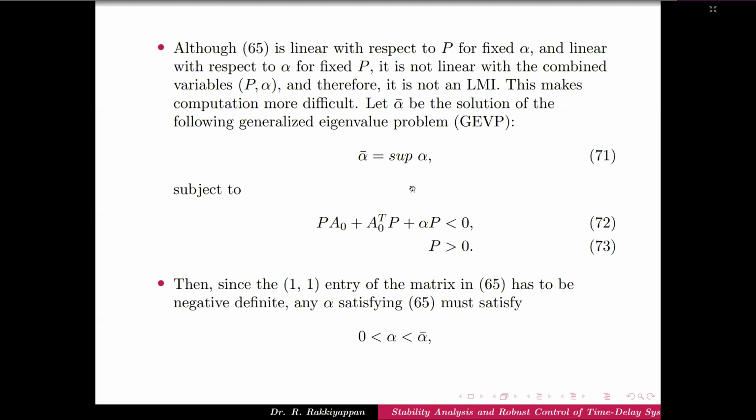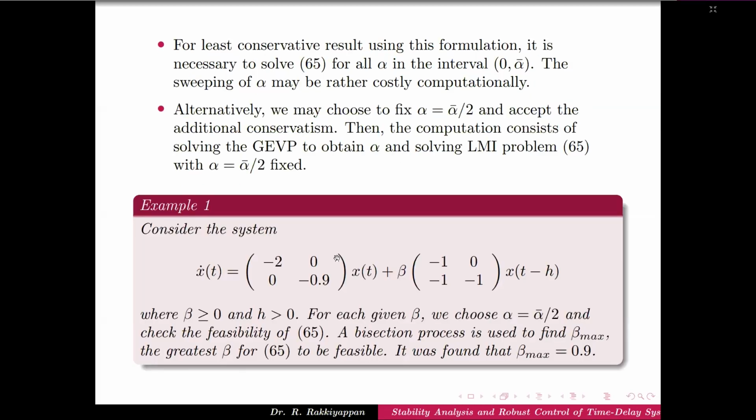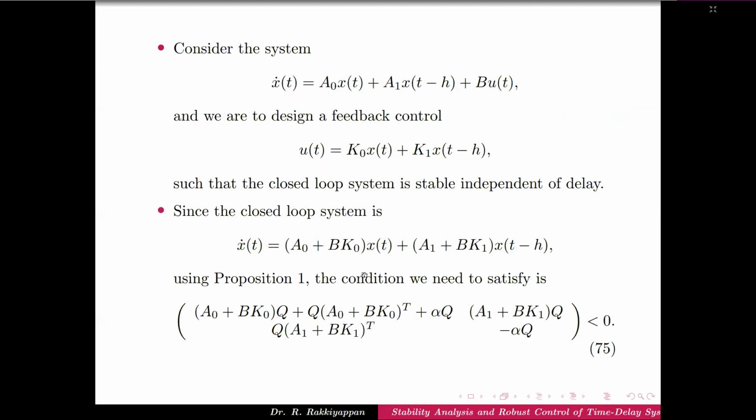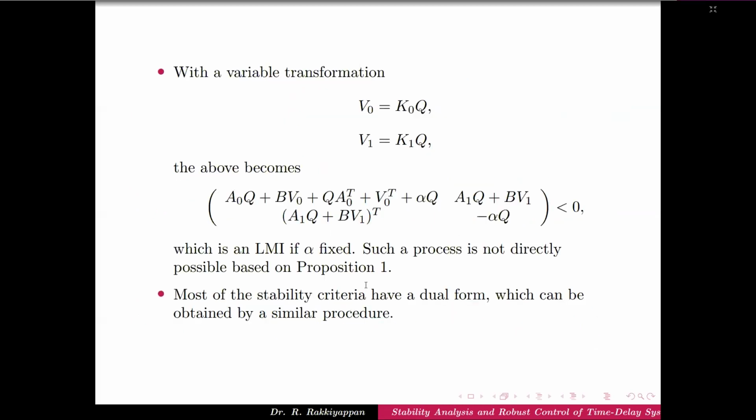It can be used anywhere, for a real life problem having a control problem or the stability analysis of a given system. So this is a simple example. Here we take the system matrices like this, and then we can achieve the linear matrix inequality in proposition 4. Solving these inequalities, we can get the stability analysis of the given system.